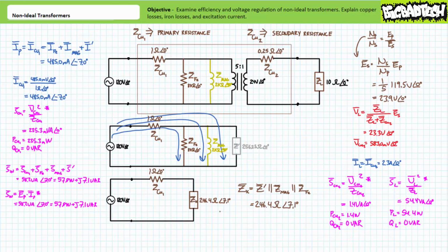You note a roughly 1-to-1 correspondence between the power consumed by the reflected impedance and the series combination of elements on the secondary. Our previous calculations using reflected impedance demonstrated a consumption of 55.7 watts of real power. Accounting for rounding imperfections in the secondary, you'll note the summation of power consumed by both the load and the series resistance is also roughly 55.7 watts.